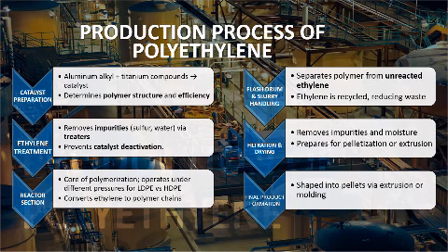Now in the reactor section, that's the core of the polymerization. It operates under different pressures which determine the category of polyethylene produced, whether LDPE or HDPE. Also, in the reactor section, the ethylene is converted to polymer chains. Now to the flash drum and slurry handling, it separates polymers from unreacted ethylene. This unreacted ethylene is recycled, reducing waste.